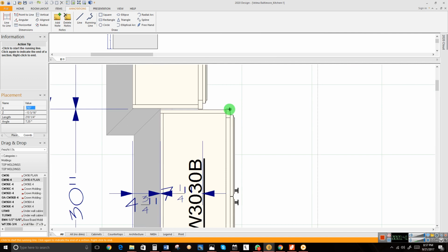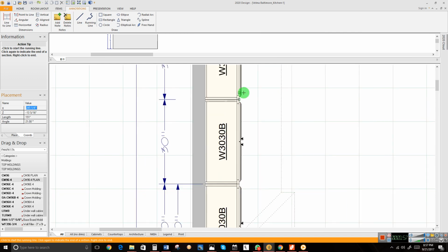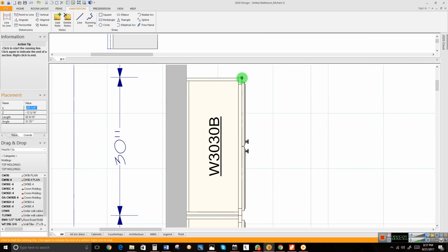Now, if you don't do that, your directions will alter. I'll show you something which I don't want to show, but it's going to give me too much headache. Look at where my mouse is right now. You click there, you wait, you move. Click there, you wait, you go up, okay? Remember, you got to wait for seconds. If not, you're going to change directions of this line. So click at the end point, wait for a second or two, and move left. Now, you click there. Now, that's the last point, okay?